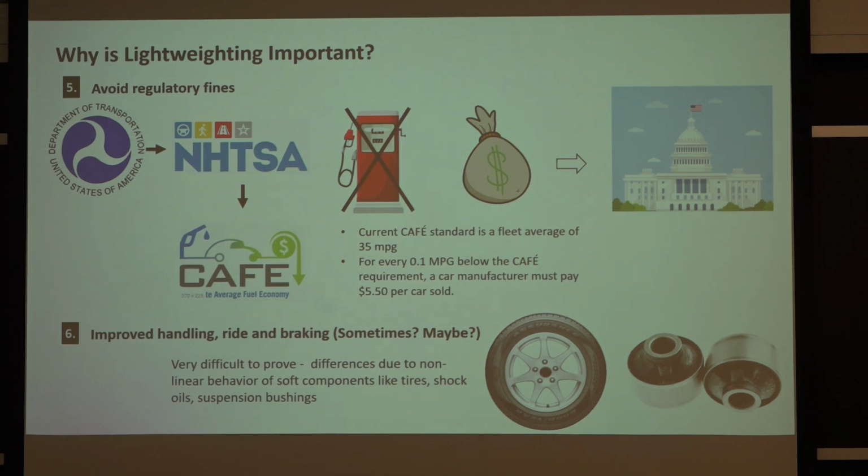If you guys are smart, you've taken statics and you understand that the friction force of a wheel, for example, under braking or turning, is just related to the normal force times some mu, some friction coefficient, right? So if the car is heavier, the friction's higher too. The braking should all be the same, and the cornering should all be the same. There shouldn't be a difference.